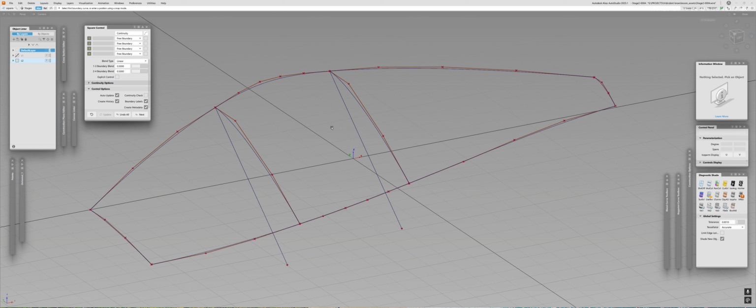If this is a patch, like you created something, you cut, rebuild, and you have some hole which you need to close, not relatively big size, and it's supposed to be natural to all of the other parts which are already created, the square tool is the best choice because it has a blend between the boundaries of the linear type. So the bias is always the same. It is a linear blend between the first, second, third, and fourth boundaries.